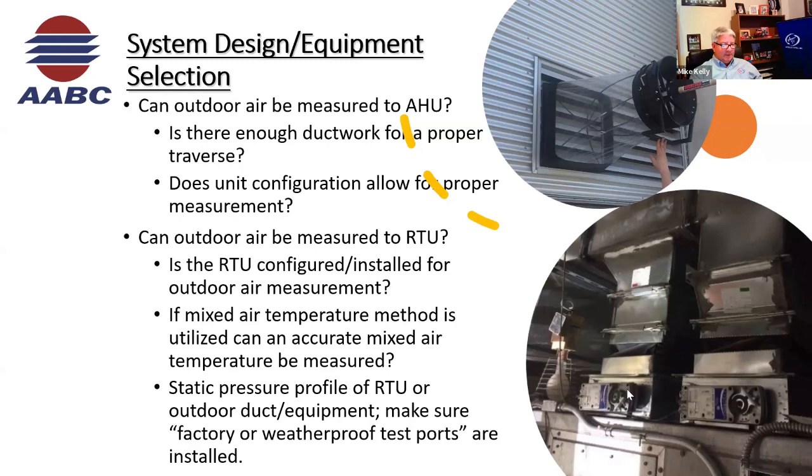Down here to the right, we have some airflow monitors, some dampers, and this is the only way we have to test airflow coming in for this big outside air. These are two outside air intakes. One's a minimum, one's the maximum. How do we test airflow coming into these? Can't get a traverse anywhere. You surely can't get in there to do velocity testing. And if you could, what would be your factor and what's the area?